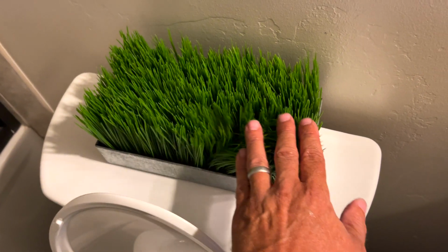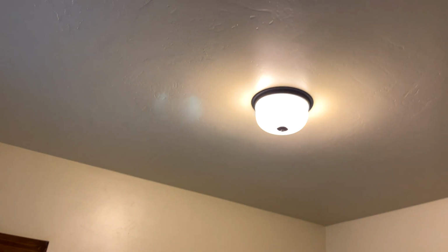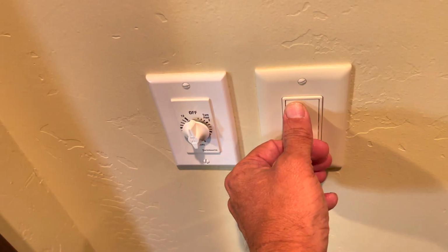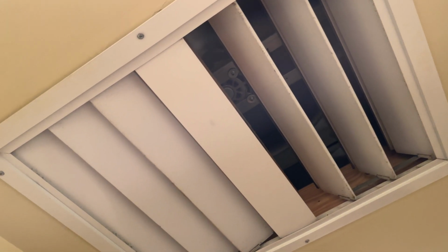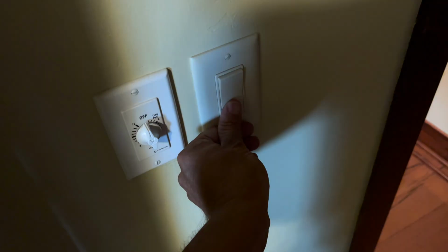And the grass was just cut. So I'm looking for anomalies on the interior. The interior goes pretty quick, just a couple minutes. Looking for major problems at the ceilings or the doors or the windows, receptacles, and the floors. Remember, there was no central cooling, and I found a fan control in the hallway. Inspection restriction, I can't get on the other side of that fan, but that's okay. I can see it from here. It's functional. Cools off the house in that way.